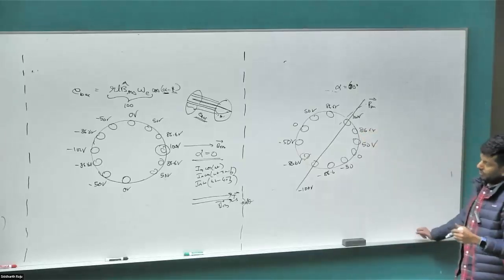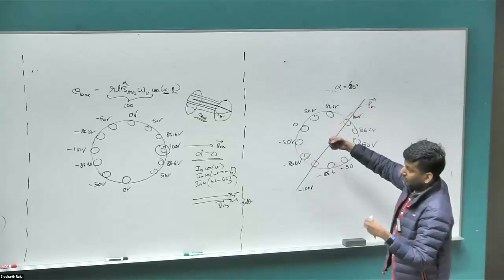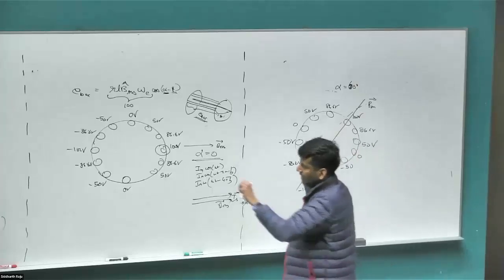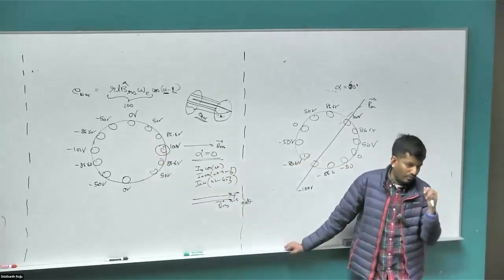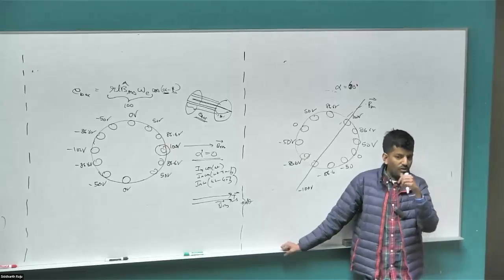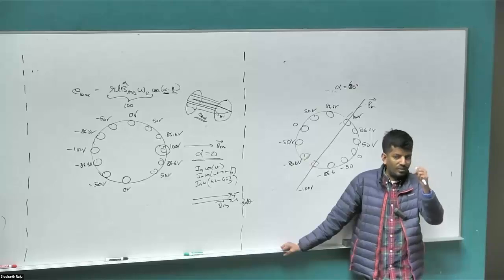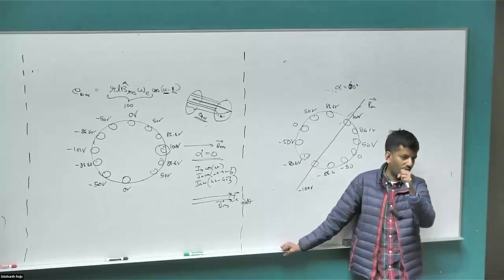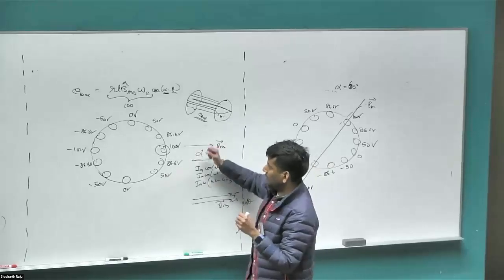Right? So what we are doing is, as the current space vector moves in the stator, due to the stator currents, the EMF of the rotor is also rotating. Right? So we have achieved two things. When we did sinusoidal distribution of the conductors in the stator, our objective was to change the current density distribution in the stator sinusoidally, which is already achieved from this diagram at any particular angle.